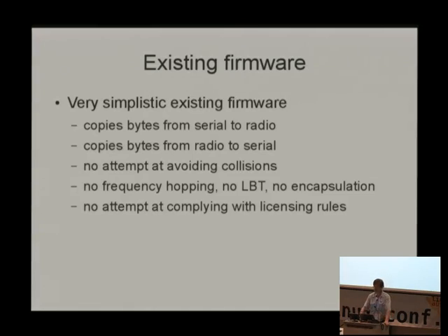These radios come with an incredibly simplistic firmware that comes from SI. And that firmware is basically, if you put bytes in the serial port, it will copy them out into the radio, into the ether. And if you receive bytes, if it sees something coming in over the radio, it squirts it out the serial port. It makes no attempt at all to avoid talking while the other guy is transmitting. So both transmitting at once. No attempt. No attempt at frequency hopping, no attempt at time division multiplexing, no attempt at all to do anything sane. It just has a way of getting bytes off the serial port and into the air, or vice versa.